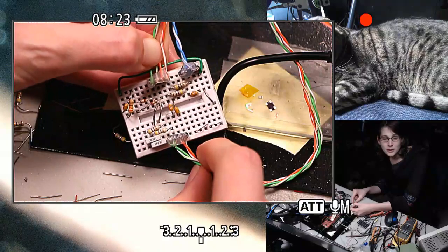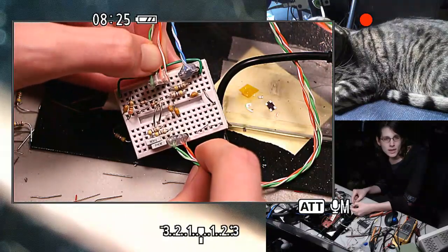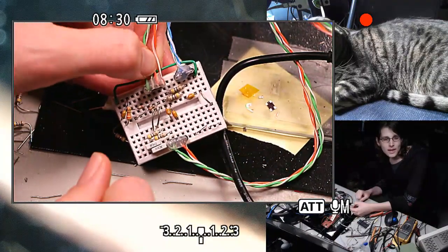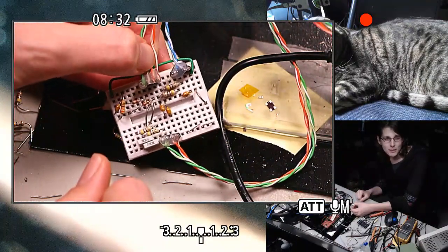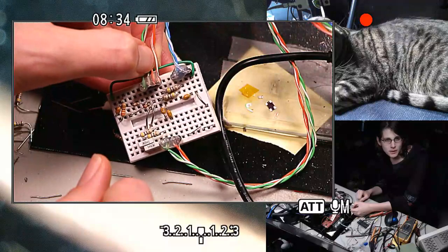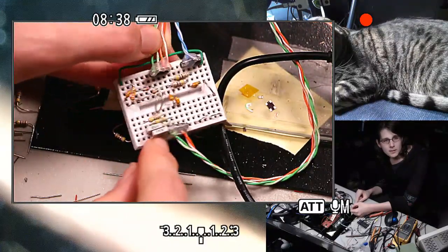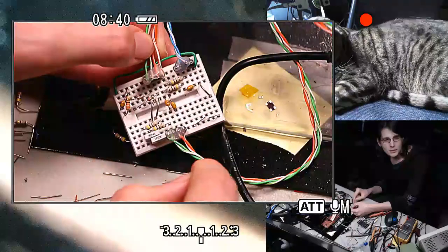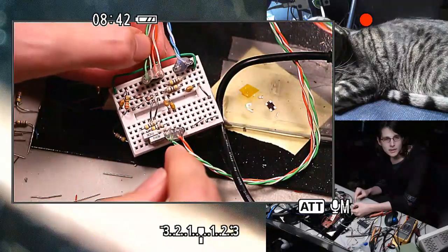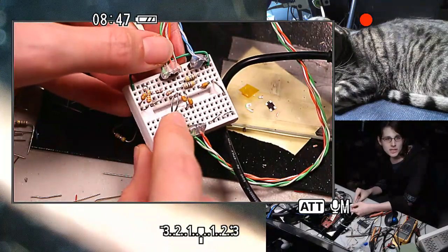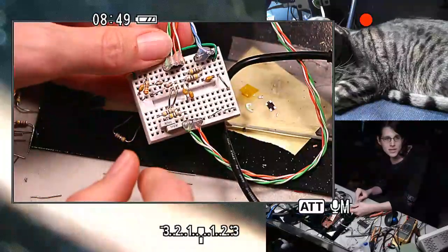Not at as deep an underclock as I'm hoping, but when I'm staying near 30 megahertz, I was having some kind of weird PLL stability problem at 30 megahertz for some reason, but I went down to like 28 megahertz. And at 28 megahertz, I was able to get a packet across the capacitive coupling into the TI chip, and then the firmware responded, and then I started experimenting with cleaning up that capacitively coupled signal.